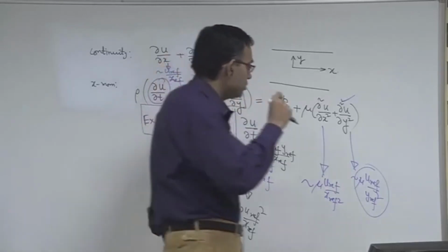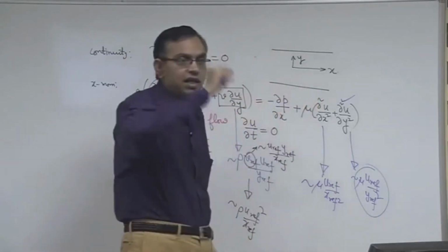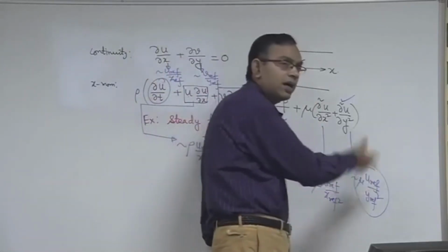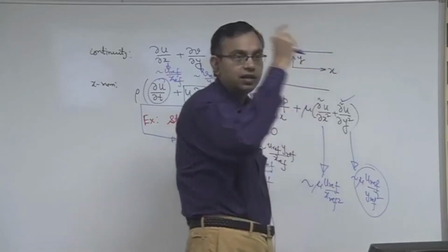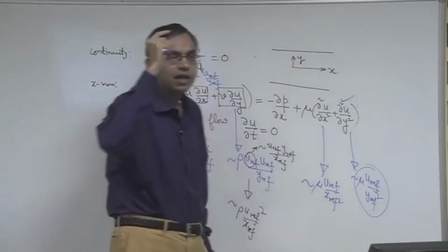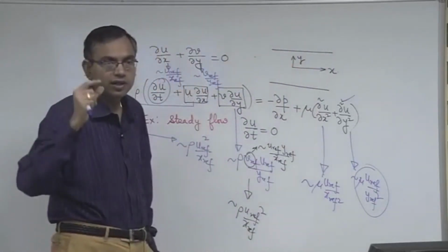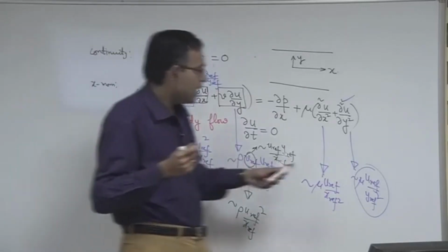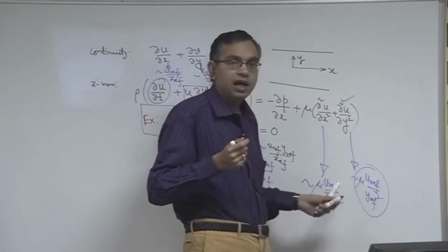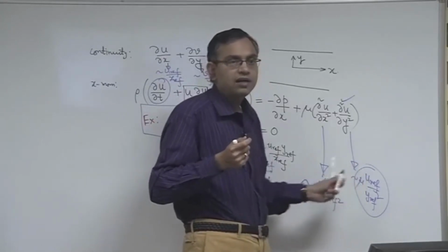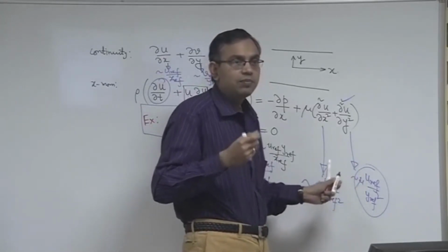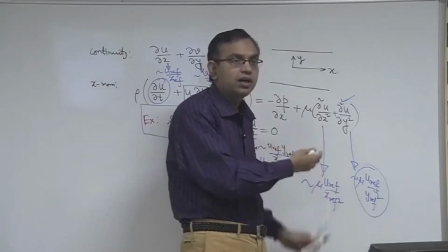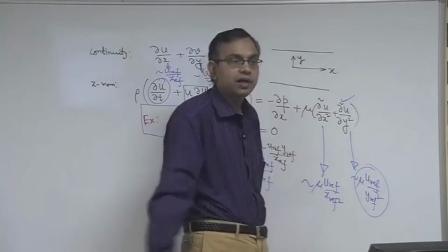So, there the delta is a naturally evolving length scale. Here the y reference may be governed by the confinement height of the channel. The microchannel confinement can decide or dictate what y reference is. Although scale-wise the treatments are very similar, you have to understand very carefully that boundary layer theory is valid for high Reynolds number, whereas here we are doing low Reynolds number hydrodynamics.